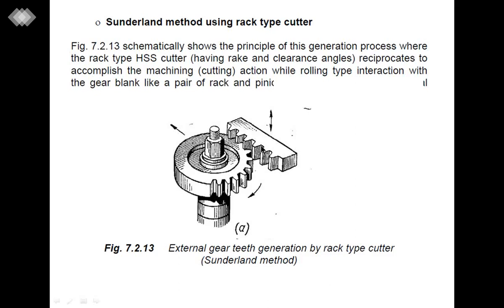After the reciprocating of this rack engaged with this gear blank, it cuts the teeth on this gear blank, and as the cutting action happens, this gear blank is indexed to the next tooth space, and it continues till the manufacturing of all the teeth on this gear blank.